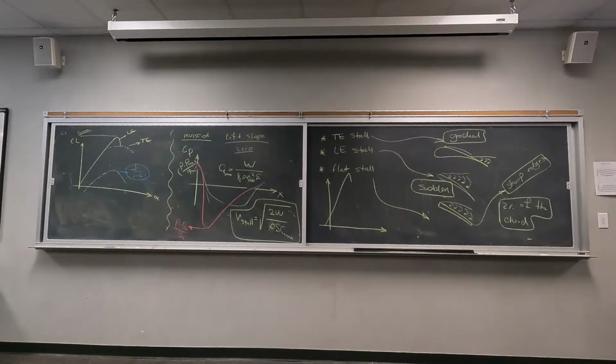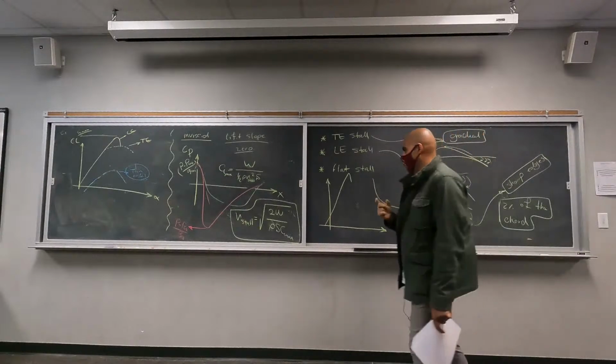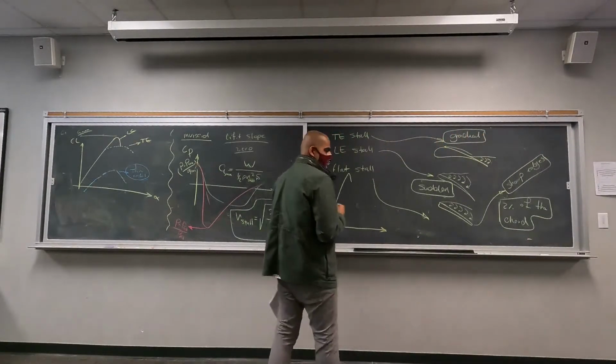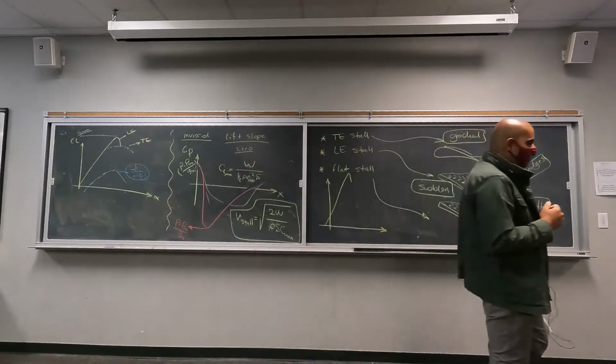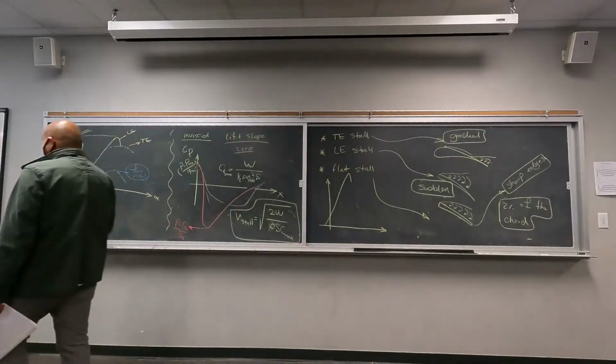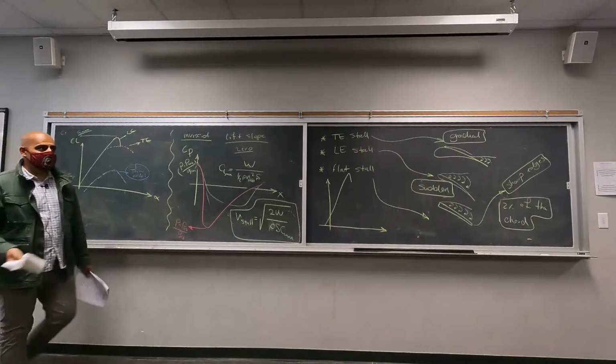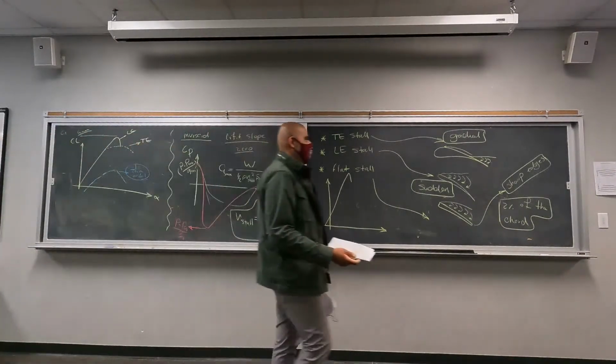So you want to change the flow separation, right? We also have another mechanism to increase the lift. What was that? We actually have discussed this in the beginning of this chapter. Think about it. One mechanism to delay the stall is to come up with some sort of a design that delays the flow separation, right?